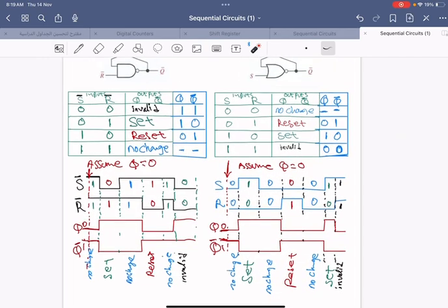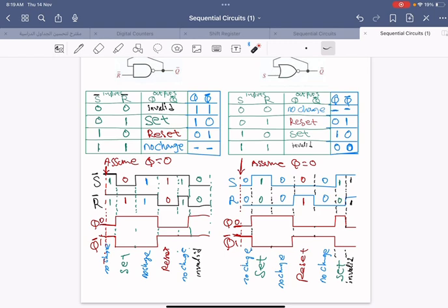In this diagram, we illustrated two timing diagrams. Suppose that we have S and R, and we need to complete the waveform diagram. We should assume at the beginning that Q equals 0. Most of the time we're assuming that, so it begins with 0 and 0, as you can see here. 0 here and 1 here, which is the opposite. Beginning is here, actually. Then let's see. We apply 0, 0, 1, 0 here, and 0, 0 here, 0, 1 here, 0, 0, 1, 0, 1, 1.